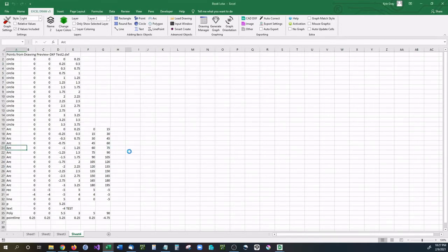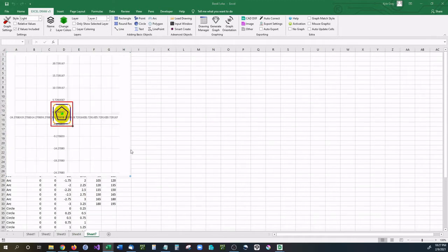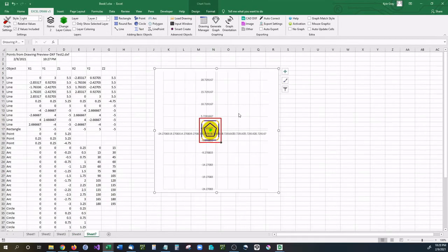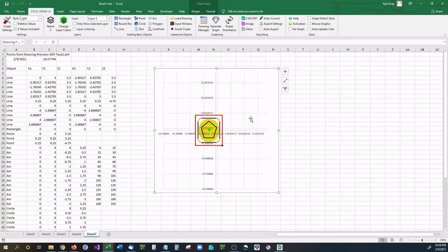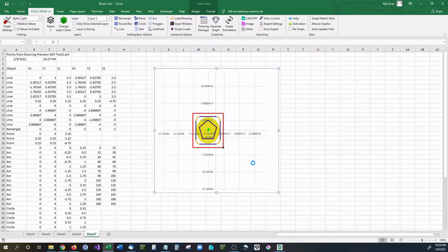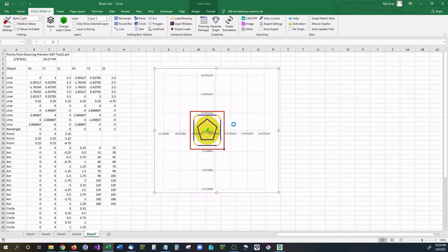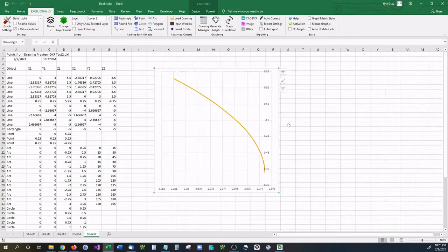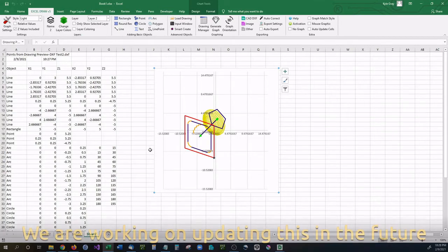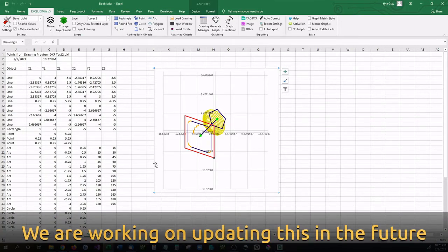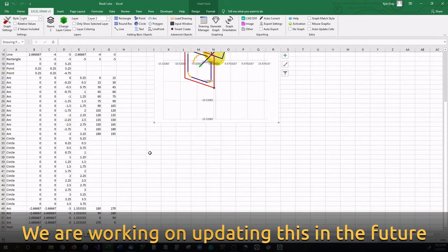And as you can see, sheet 4, it's going in, it is adding everything in, and there we have our drawing. So I'm going to pan this over here so we can see it better. But yes, we have inserted a drawing, or we loaded a drawing in, and Excel Draw has gone in for us and added the objects in, and now we can see that we have our objects back. Whenever you import a drawing using the load drawing, it will not save the layers that it is on, so it will automatically put into whatever your default layer is selected to.